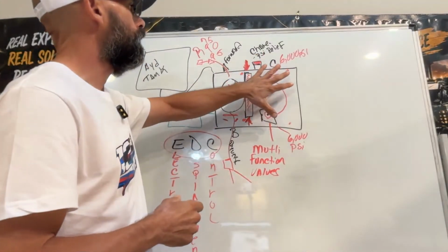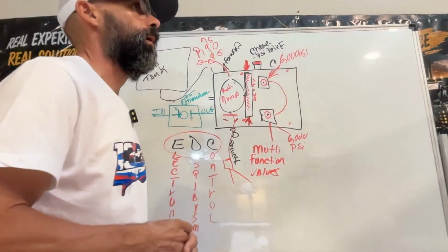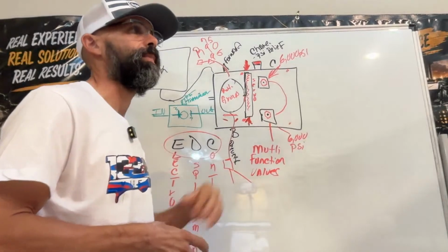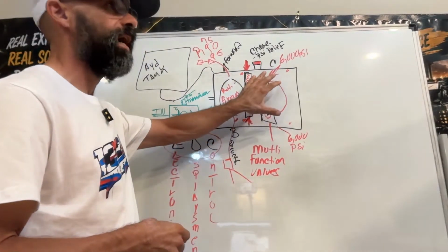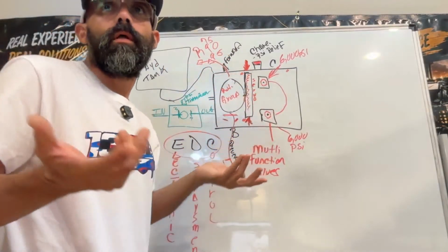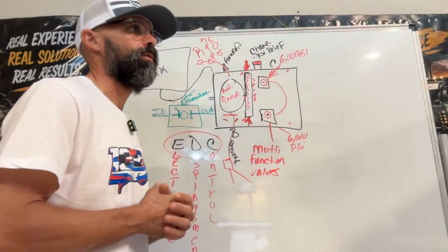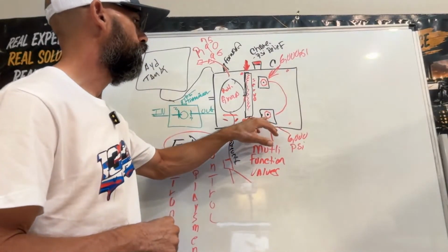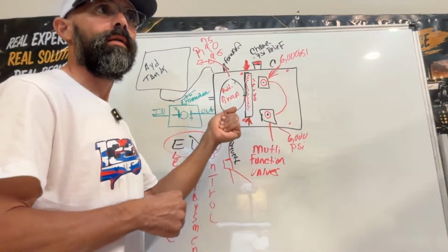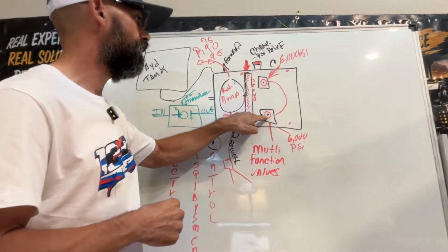Some people say, just lower the pressure because I want to protect my equipment, or they're driving down too fast, depending on the type and model of equipment the pump is mounted on. So all you have to do is put a wrench on the jam nut, loosen it, and hold the jam nut on the multifunction valve.